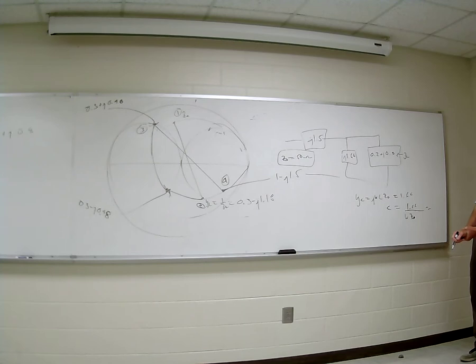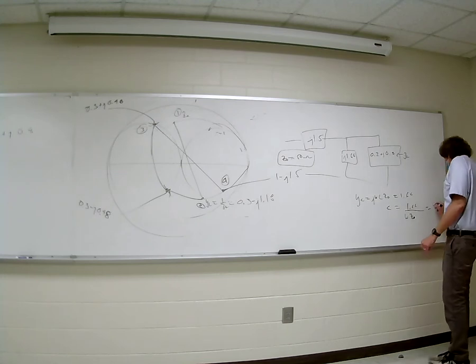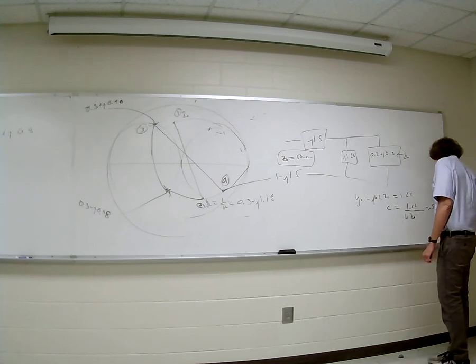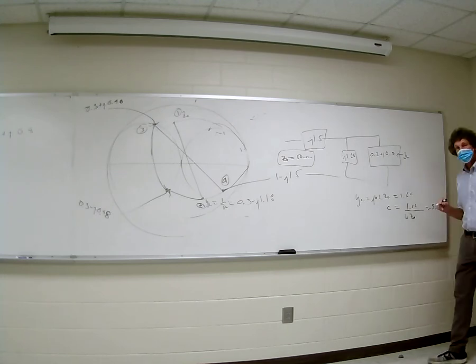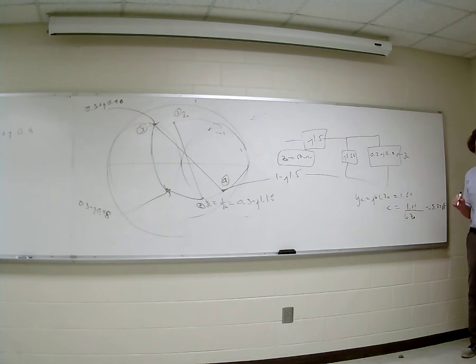So it'd be 1.66 over 100 pi times 10 to the 8. Around 5.28 picofarad. That's a small thing, but it sounds right. Is that right, guys? All right. So that's the capacitor. Somebody, not me, how do we get the inductance value?